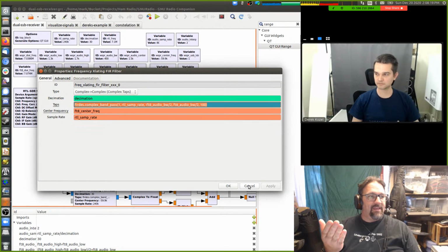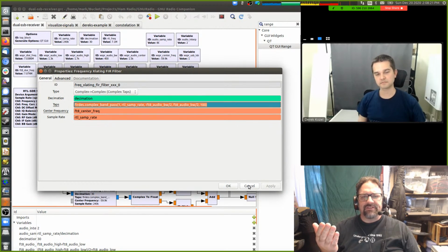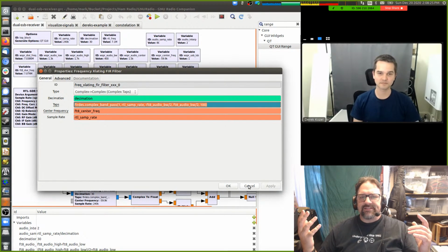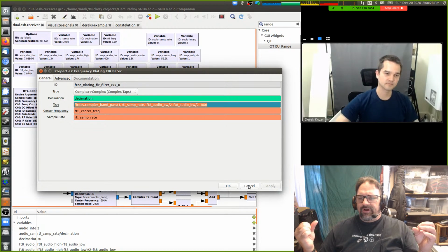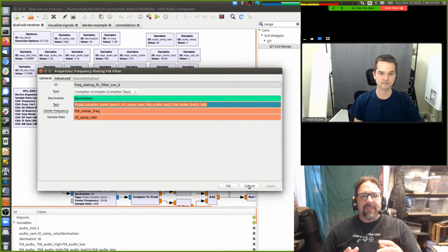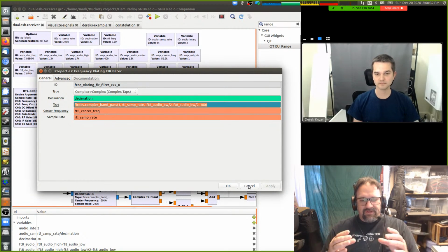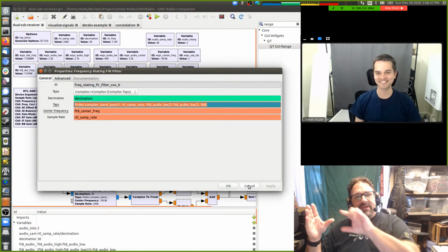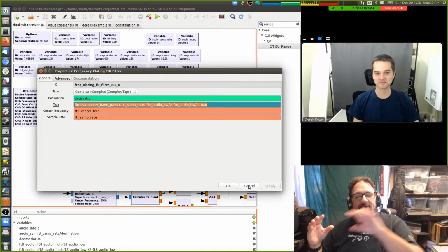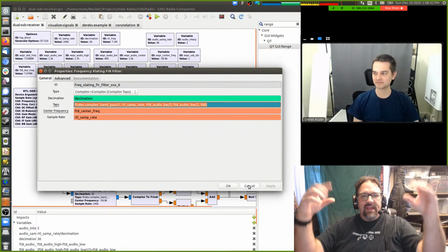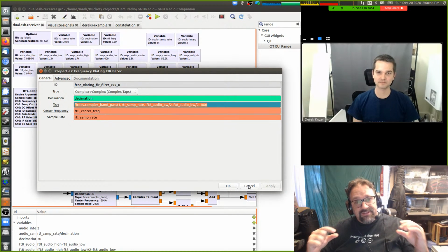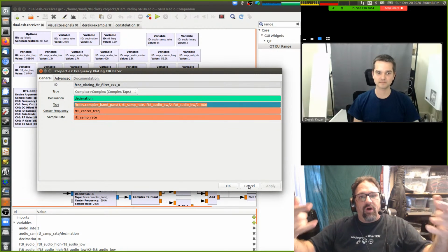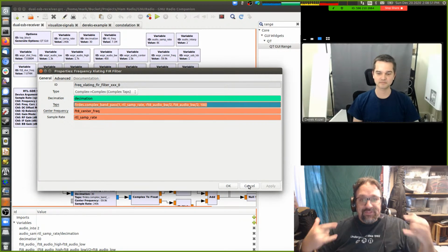Similarly, like the SSE functions, the super advanced parallel vector math functions that the Intel processor has. I can't remember what they're called, but you might have a 64-bit word, and that 64 bits is actually 4 16-bit numbers. I want to take these 4 16-bit numbers and multiply them by this other 64-bit representation of 4 16-bit numbers and perform all 4 of those multiplications at the same time.